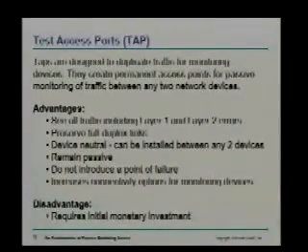Taps also fail open to the network. So again, we talked about relays earlier, about that link zero delay and that link fault detect. They should always fail open to the network so that if you lose power, on a copper device that is, you are not going to take down the network link.